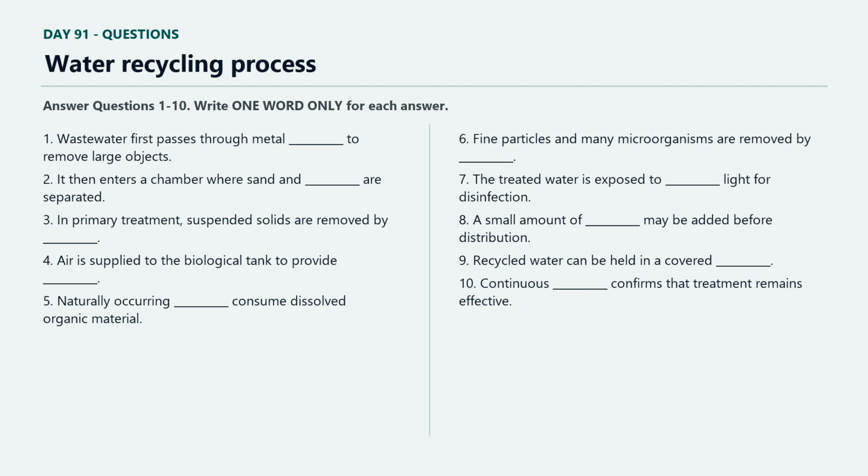Incoming wastewater may contain cloth, wipes, plastic, wood, and other objects that could block pipes or damage equipment. The flow therefore passes through metal screens with openings designed to trap these large materials. Coarse bars remove the largest objects, and finer openings may follow to capture smaller pieces. Mechanical rakes clean the trapped material from the bars so that water can continue moving. The removed material is washed, compacted, and disposed of separately. It does not become part of the recycled water. Screening protects pumps and valves, but it does not remove dissolved pollution or very small suspended particles.